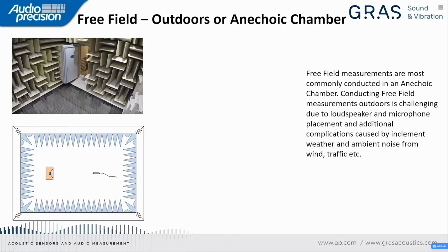In fully anechoic chambers, an acoustically transparent working surface above the floor wedges is usually provided by means of an open steel wire mesh suspended from the walls. An anechoic chamber approximates a free field above a lower limiting frequency, determined mainly by the length of its wedges.